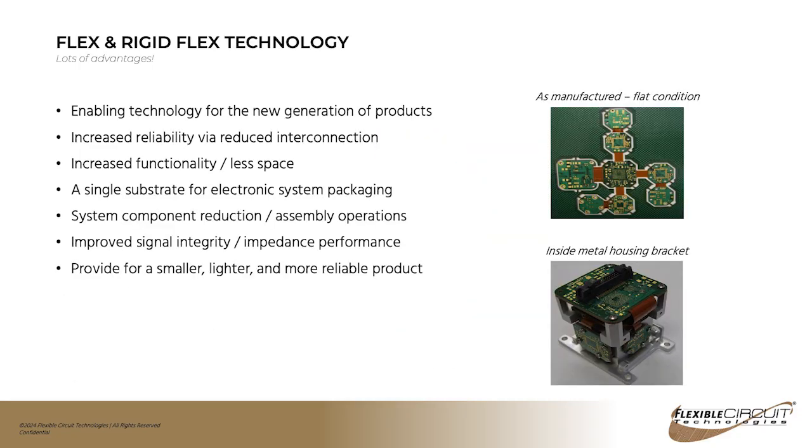There's a general misconception by a lot of people that flexible circuits are used to replace standard rigid PCBs, when in reality, flexible circuits are used to replace wires. The main reason for this is that wires and wire harnesses have to have insulation around each individual conductor, and flexible circuits are able to do that in a much more space-efficient manner.